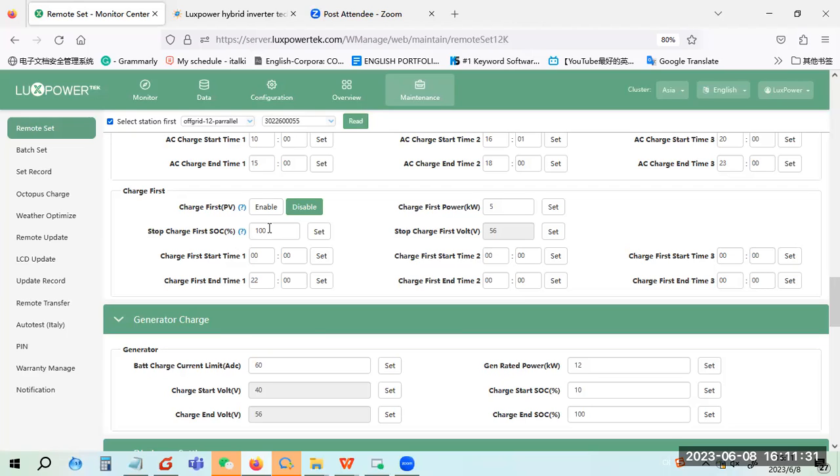For example, if you set 100 here and the solar battery has already reached 100%, then the power will be used to take the load since the battery is already full. Or even if you set 90% here, then if the battery reaches 92%, the solar power will be used to take the load first. So this condition is to stop the charge first.